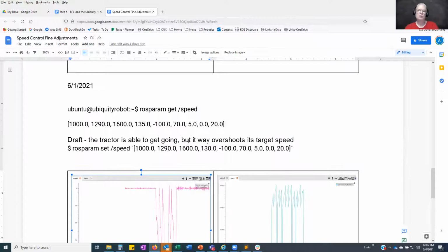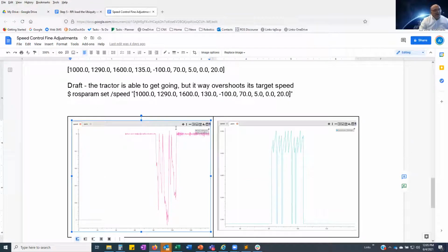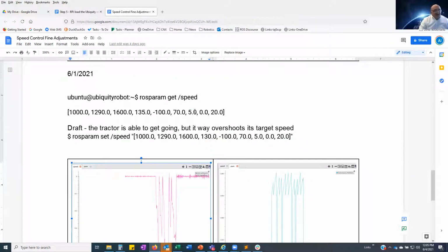That's the actual measured speed off one of your back wheels. It is, and I varied. I mean, this is just one screen print, and it's just one setting of the two variables that basically are ingested into the code, which, I know it's not a real PID, but it's labeled as KI and KP.